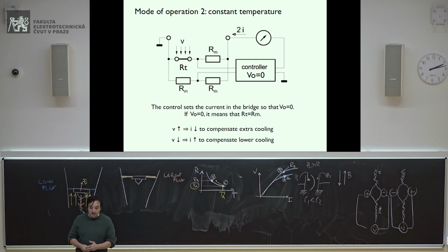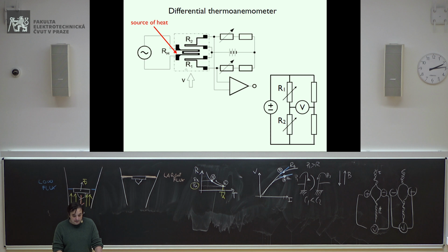In this way, what you do is not to measure the resistance itself, is not to measure the voltage output of the bridge as a measurement of the stream of water. What you do is to measure the amount of current you have to inject in the thermistor, to have always the same temperature. And this depends on the stream that you have of the water in the pipe, okay?